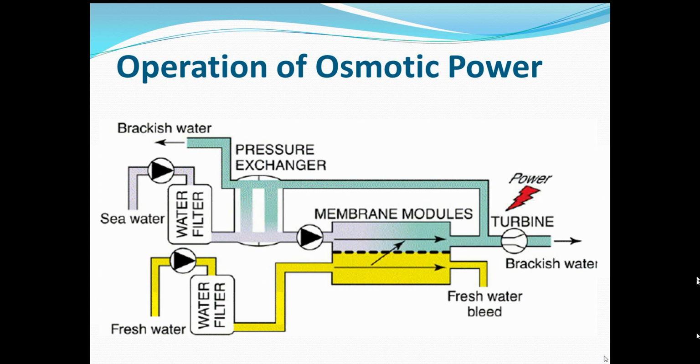The pressure that gets developed is sufficient to create a head of 120 meters. This pressurized water is made to flow through the turbines. This jet of water in turn helps the turbine blades to rotate, thereby generating electricity. We can harness this through a generator.